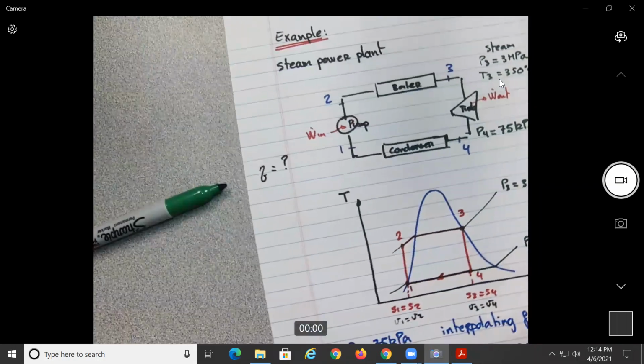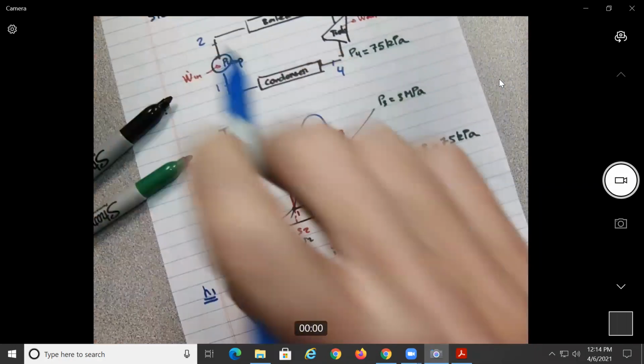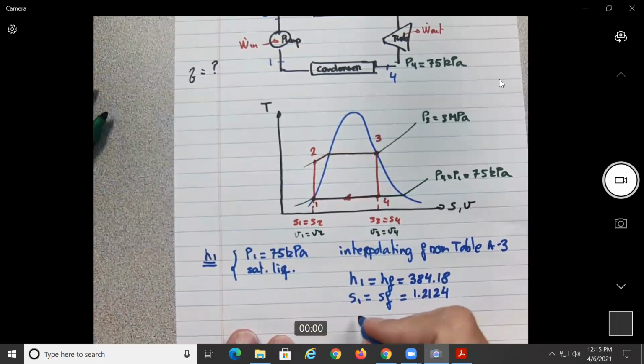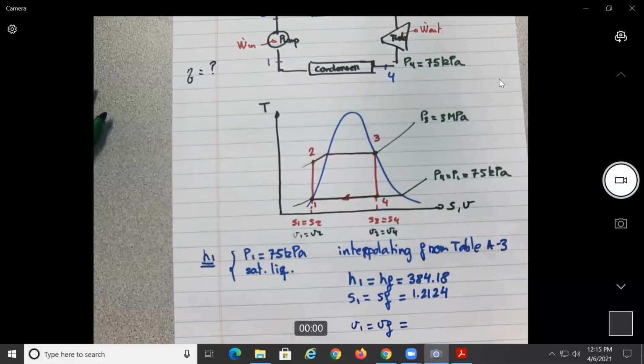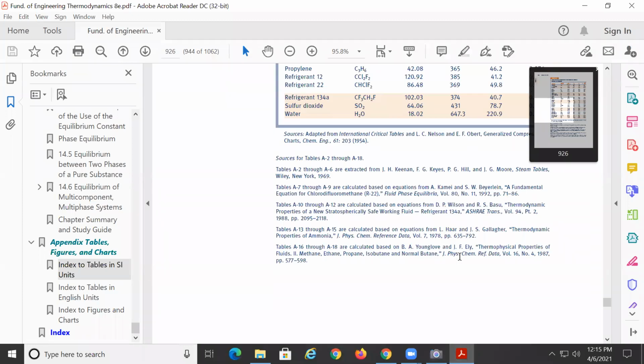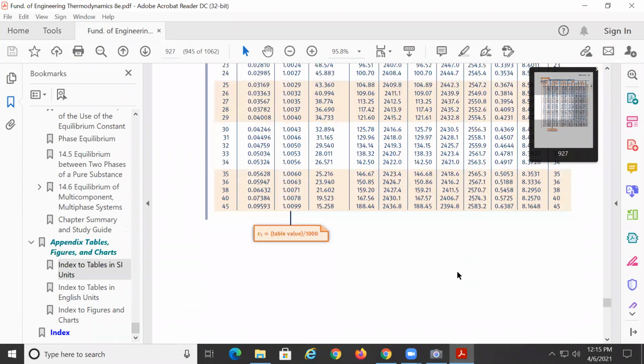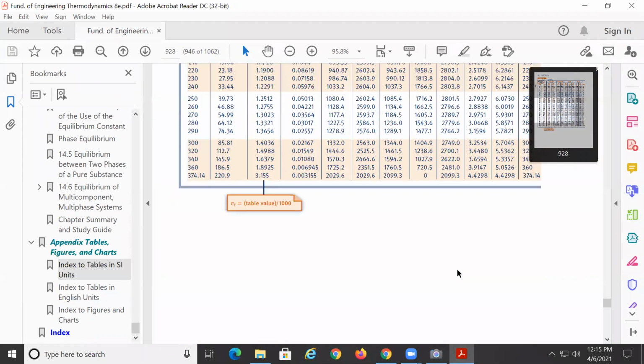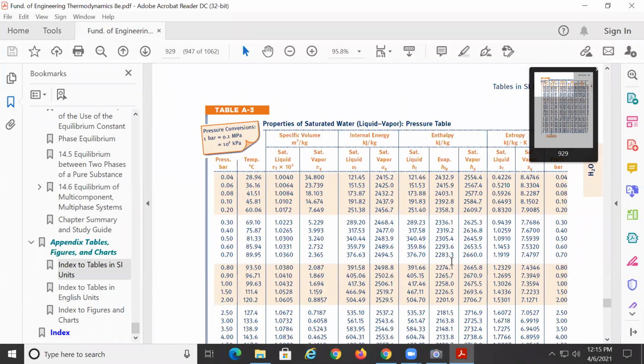So that means, sorry for that, you're going to have to give me another calculation here. That means here that V1 will be equal to V fluid. You have to give me that value. So that would be what? Table A3. We might go faster this way, table A3. So we were at 0.75, you need to do both of them. So V fluid will be, careful here, 1.036. Okay, so it's 1.037.